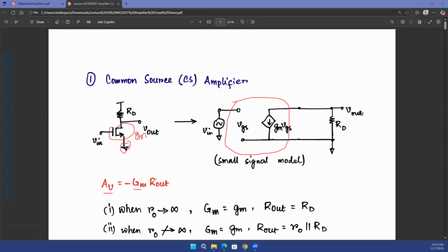Again, remember that whenever we talk about gain in this class, we're talking about AC gain. So our output current is output AC current, input voltage is input AC voltage. We're not talking about DC anymore because the DC biasing is something I'm assuming that you guys can do. And what that means is putting the transistor in the correct operating region, that is the saturation or the active region. And then we'll use all the active region equations to come up with the gain. Now, Gm, that is transconductance, that's output AC current divided by input AC voltage. Output AC current multiplied with output AC resistance. Remember that this Rout is again output AC resistance. It's not the DC resistance.